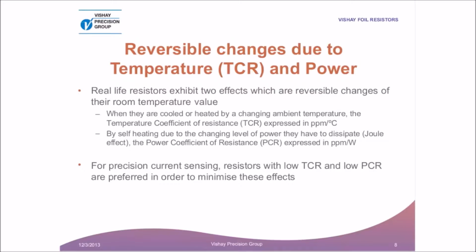Just an interesting side note, thick and thin film resistors permanently shift value after being exposed to a large temperature excursion or power. It's a permanent shift, and it will happen initially and continue to happen every time the resistor is exposed to the phenomena.